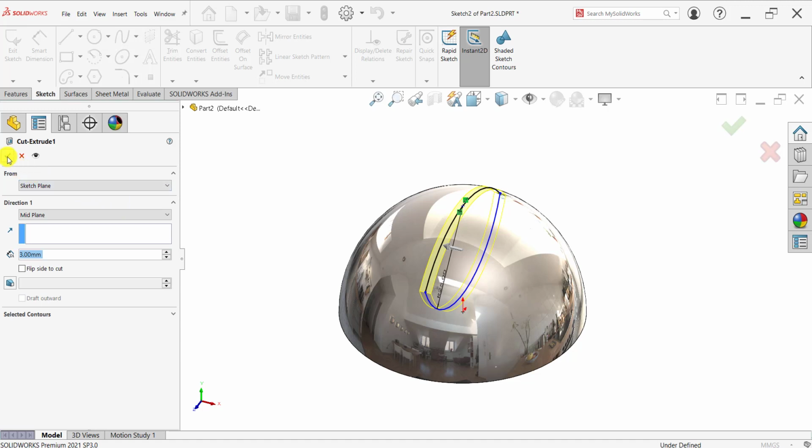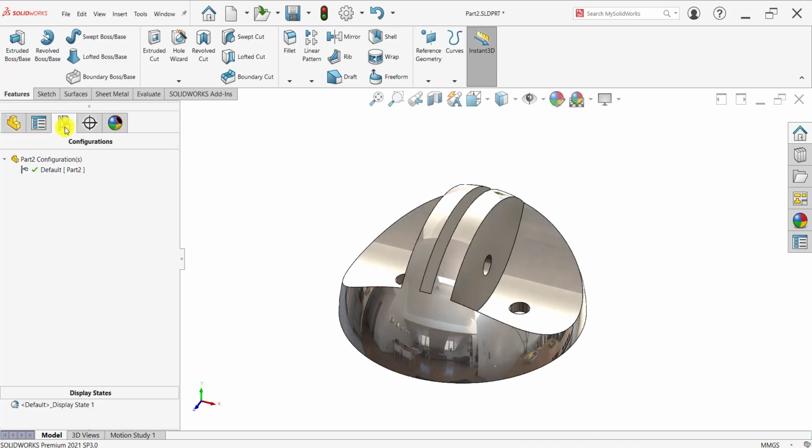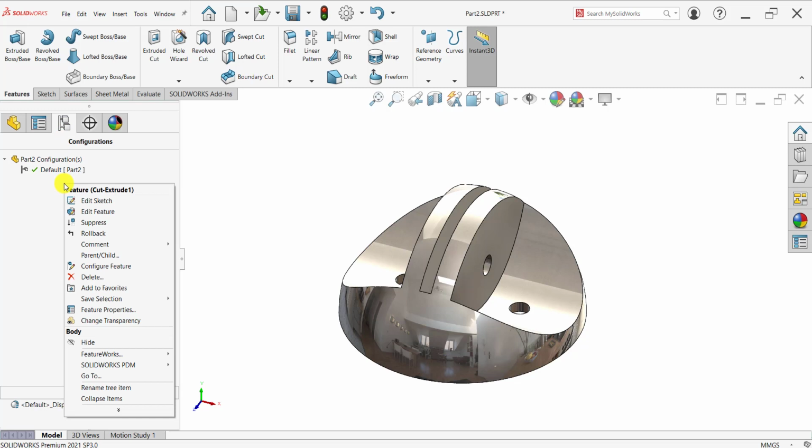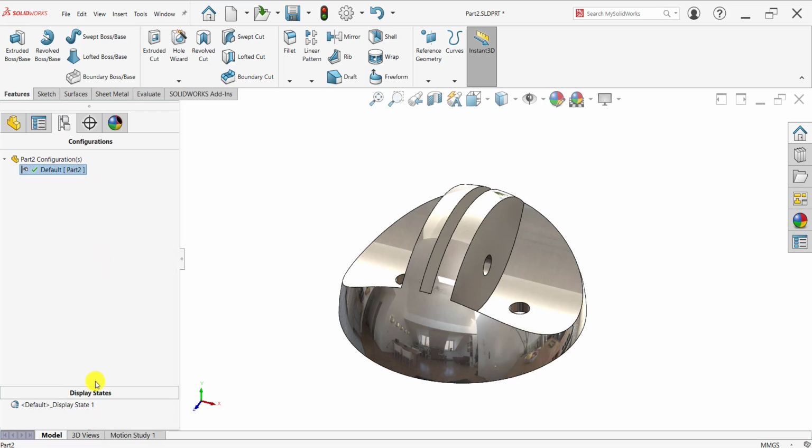The Configuration Manager is a means to create, select, and view multiple configurations of parts and assemblies. You can split the Configuration Manager and either display two Configuration Manager instances or combine the Configuration Manager with the Feature Manager design tree, Property Manager, or third-party applications that use the panel.